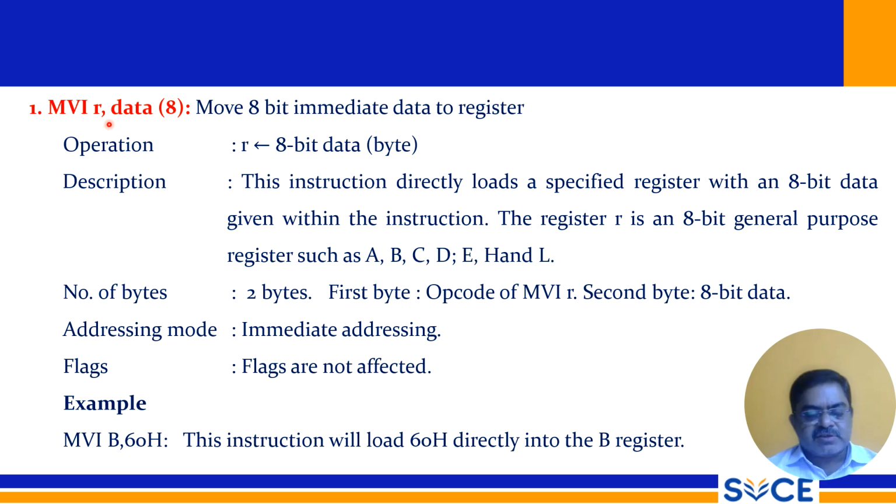Only for the instructions that start with the letter S, students, there is one blind rule you can remember easily. In the instructions that start with the letter S, the data flow takes place from left-hand side to right-hand side, opposite to this. Now it is happening from right to left, and I will show you those S instructions. Only in those instructions, please assume, or you can confirm, that the data flow takes place from left-hand side to right-hand side.